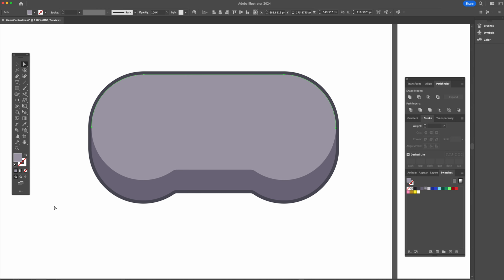All right, so now I'm going to give it that lighter color, just from this anchor point to this anchor point, a light gray. Again, I need to change this to be within a stroke and not a fill, so I'm going to hit Shift X to swap those two properties and then add some width to it.